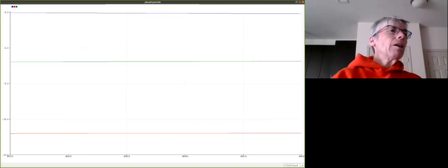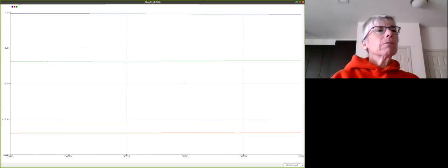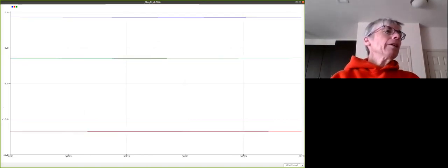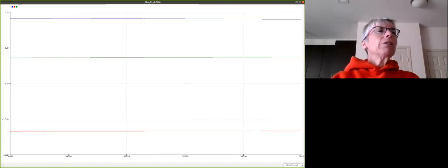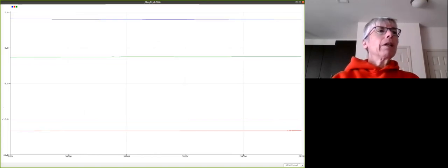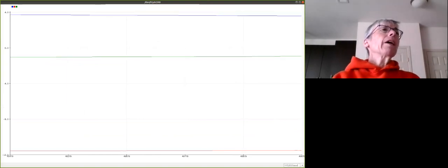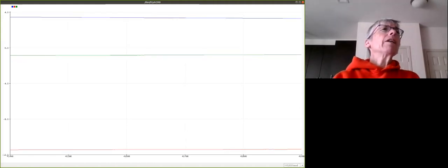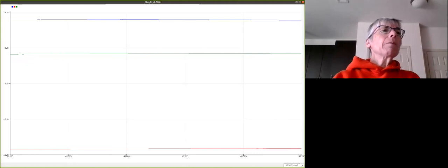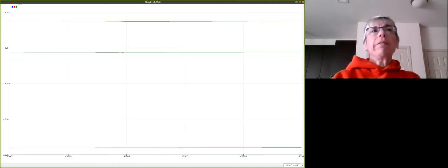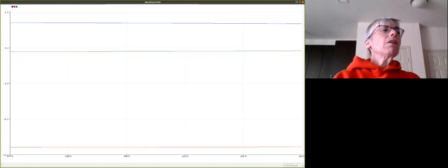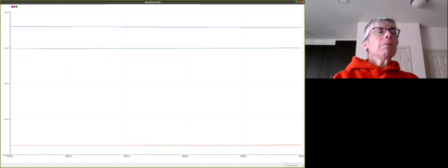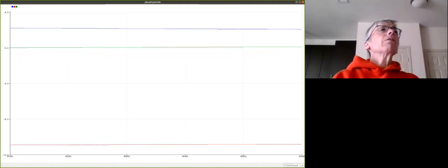We actually need something like a magnetometer. A compass is easier. I need to say a compass. I can't say the other. To measure that change in magnetic field usually gives us a better yaw reading. Roll and pitch, we usually get a decent reading out of the gyroscope. Not sure which is which here. They're all gravitating very slowly back towards 0. It's been quite a few seconds and you can see that they're slowly making their way back towards 0. It's taking a long time to get rid of that error that was summed over that period in the gyro.